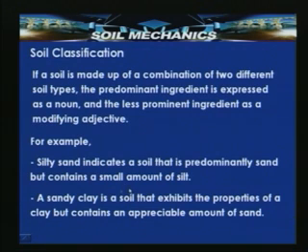a modifying adjective. Similarly, a sandy clay is a soil that exhibits the properties of a clay, but contains an appreciable amount of sand. So, if a soil is made up of a combination of two different soil types, the predominant one is expressed as a noun and the less predominant one is expressed as a modifying adjective. Examples are silty sand or sandy clay.